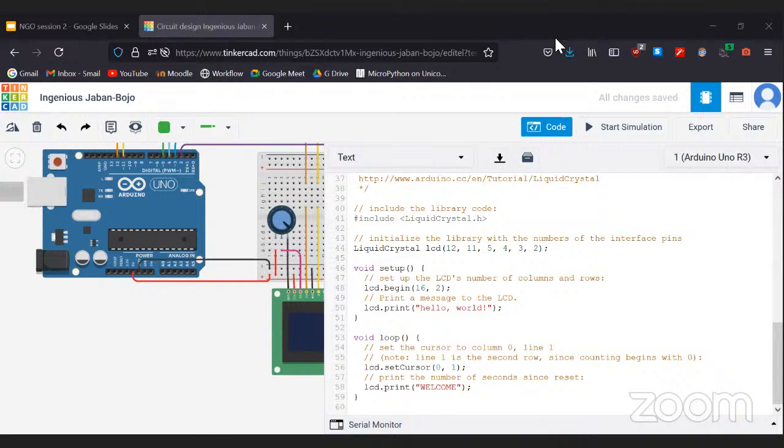Okay. So the pins in the Arduino, they are not written negative. Wait, by that you mean the tilde? You mean the tilde operator, right? Those are basically for PWM, that is pulse width modulation. Suppose you want to give an analog output; the pins with that symbol that Ajal just put in the chat box signify that you can give analog output using the digital pin. Some objects might need an analog signal, and you use pulse width modulation to convert digital signals to analog signals. So it's not a negative sign.